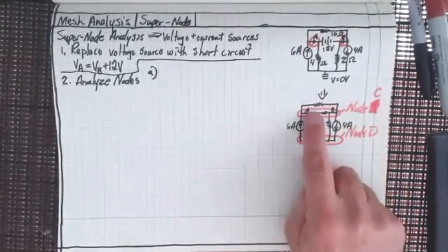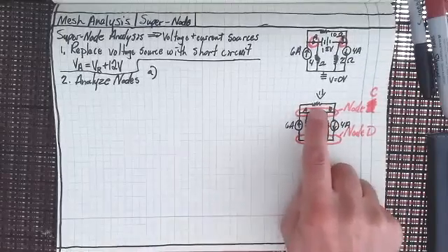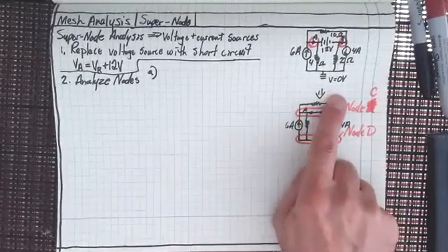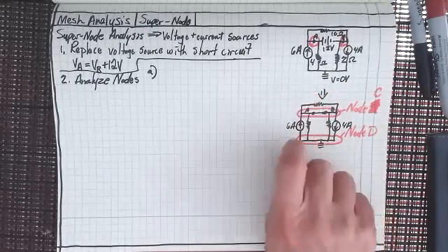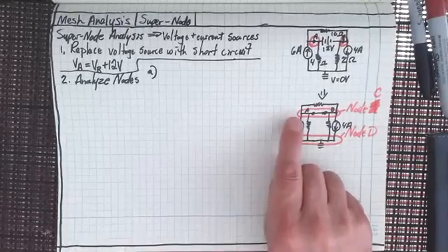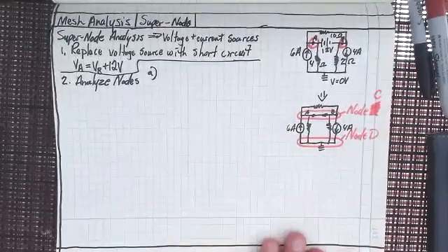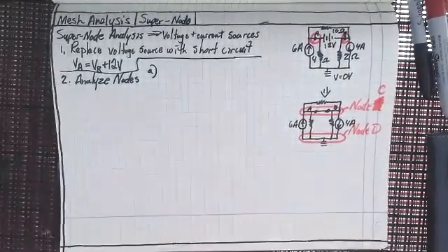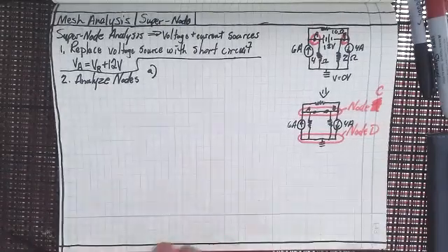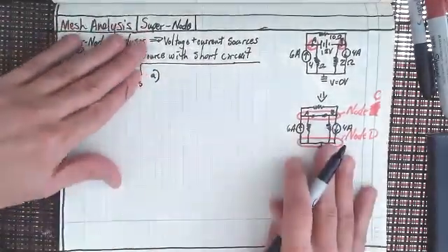If I'm going around a loop and I look at a resistor, I look at it as a voltage drop. I don't look at it as a voltage increase. I also look at current that's flowing into a node as a positive. I think your book does that the same way, but not for the mesh analysis voltages. So anyway, let's do a summation, and it doesn't matter if plus is minus and minus is plus. It's all going to come out because it all equals 0.